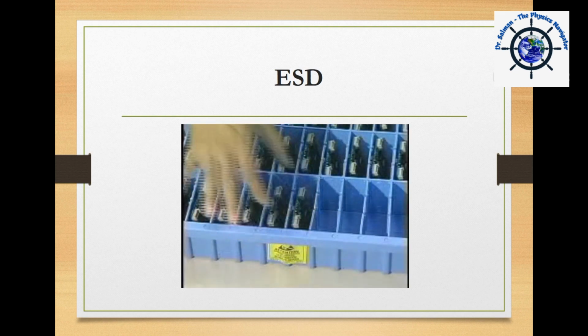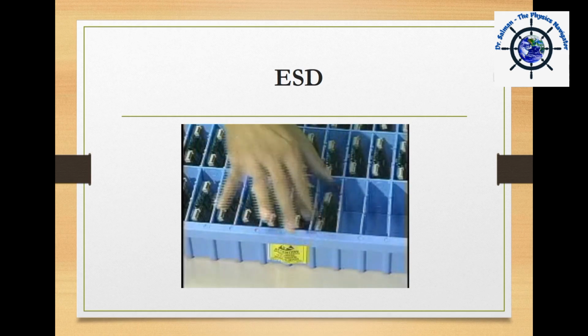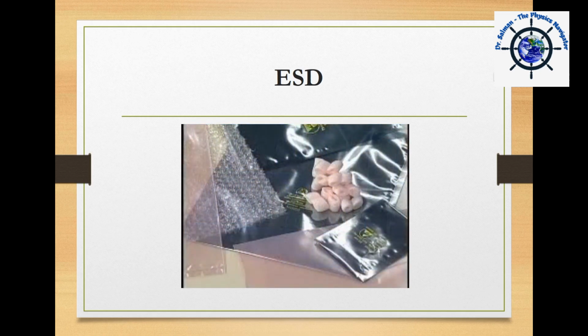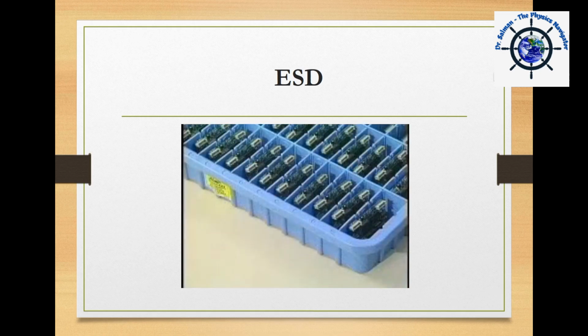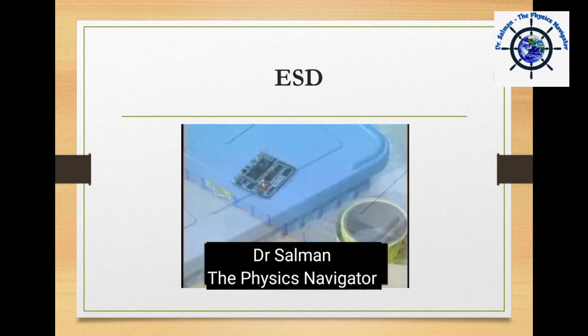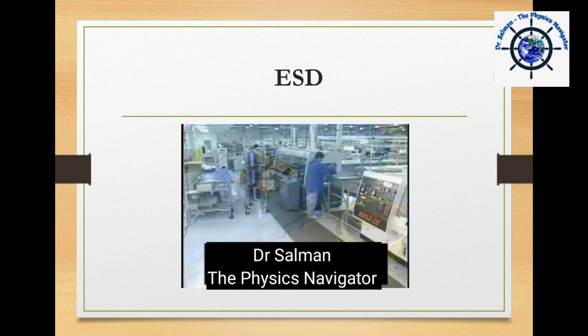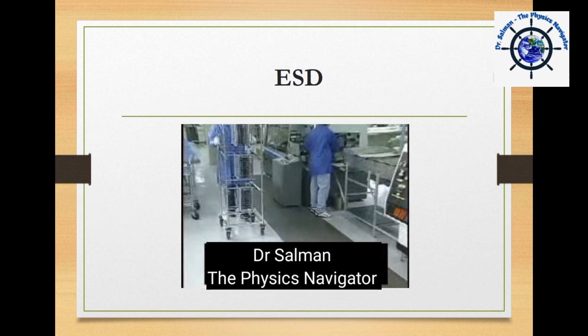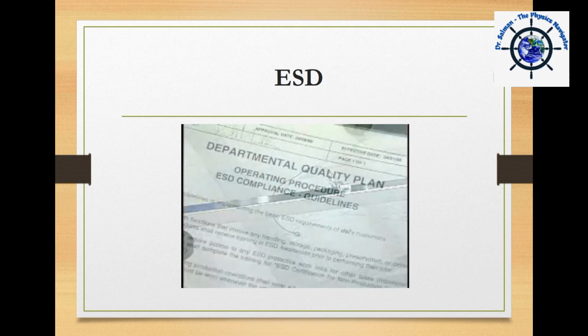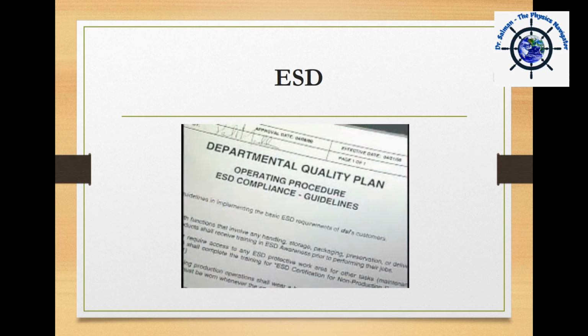It's important to use clean containers that are the proper size for the device and clearly marked for ESD-sensitive items. Use only approved packaging materials. Also, make sure the device is completely inside the container and that the container is closed. Make it a habit to not leave the item on top of or next to the container. When transporting the ESD-sensitive items, use push carts or racks that are designed for ESD-sensitive devices. Again, your company will explain its policy regarding handling, storing, and transporting ESD-sensitive devices.